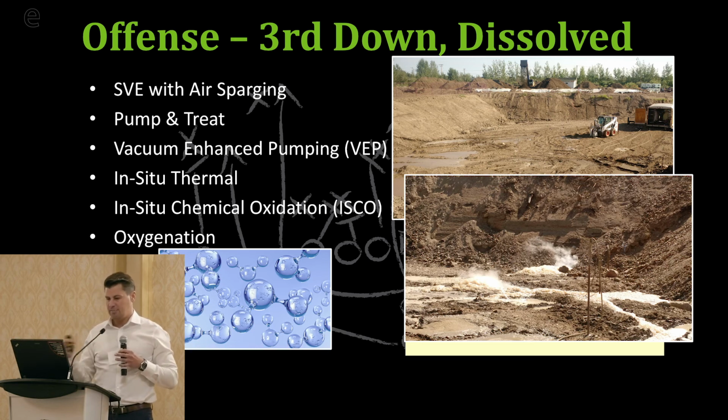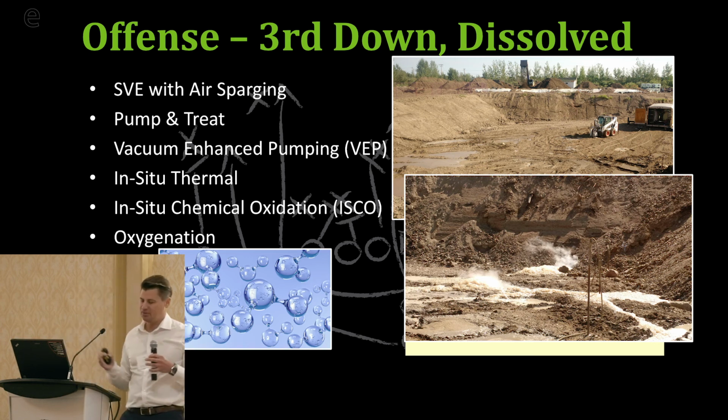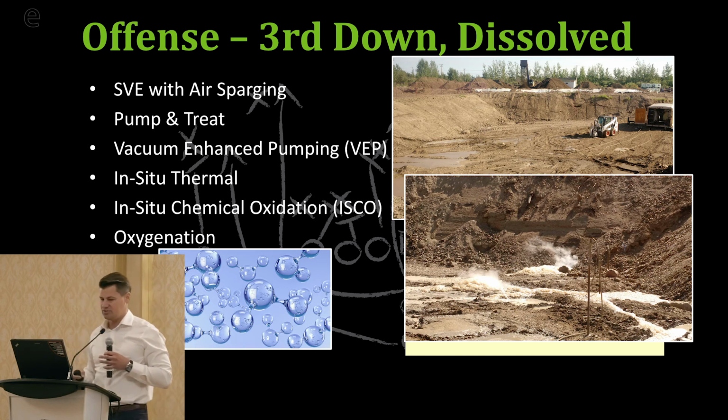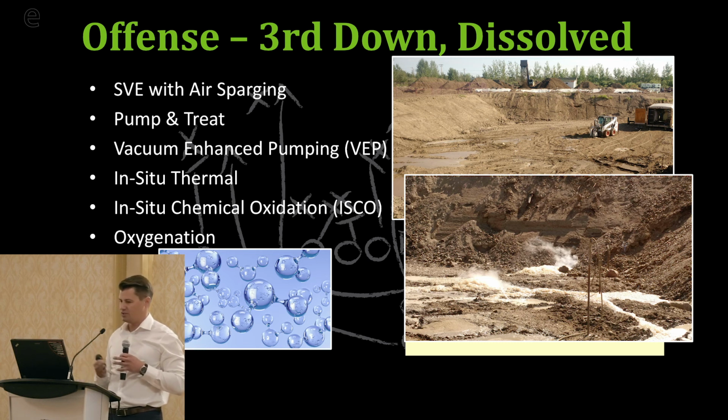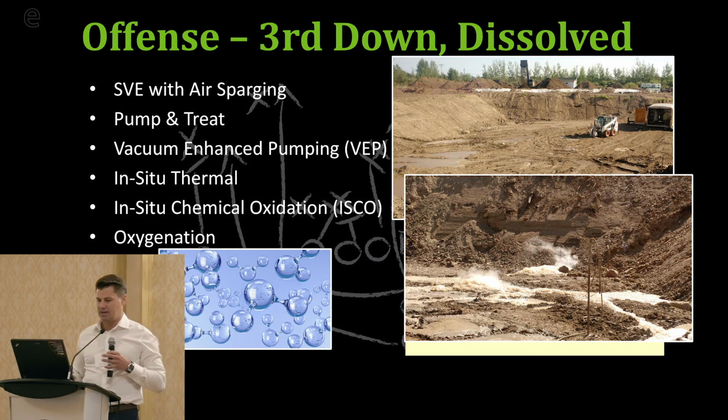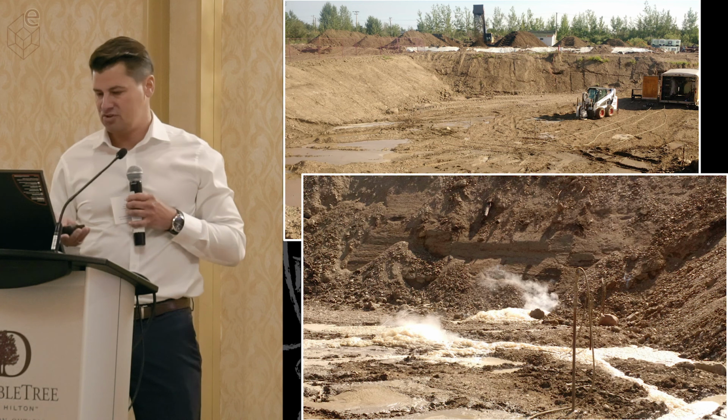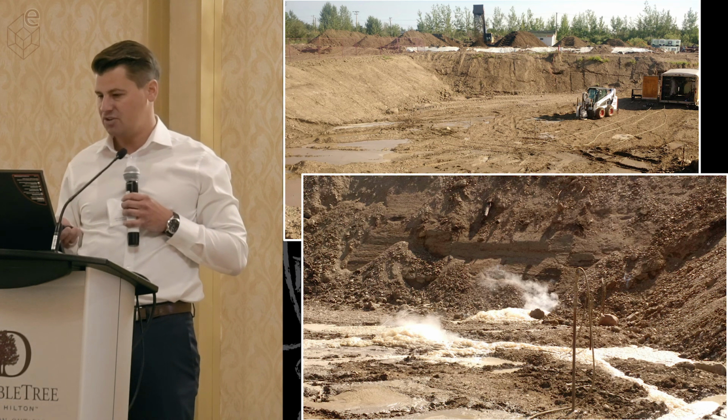The thermal, and a couple of new ones I haven't talked about yet, are in-situ chemical oxidation. So this is basically adding chemicals to treat chemicals, which isn't always the solution, but if you understand the stoichiometry, which I often don't, I'm not a chemist, it'll break down the hydrocarbons into carbon dioxide and water, and so it can be quite effective at polishing the last remaining dissolved phase you might have at a site. And then you can also promote biodegradation by oxygenating the plume, adding it using products like calcium peroxide and that sort of thing.